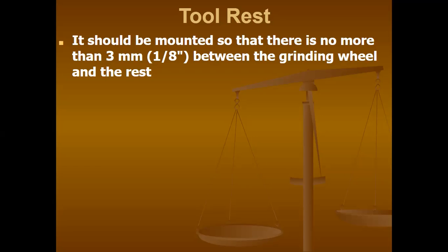So you can use gloves if you do not want to get sparks on your hand. These pedestal grinders will throw some sparks. Generally, they don't hurt you, so I almost never use gloves on these at all. If I'm working with a small piece, I will secure it in those vice grips and then do the work on it. But I don't risk my gloves being close to something like the stone and having the potential to have them pulled in.